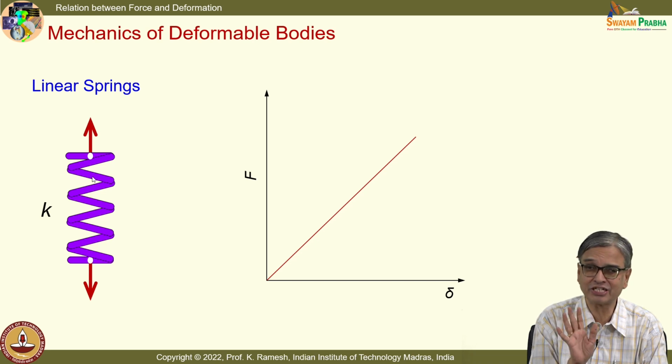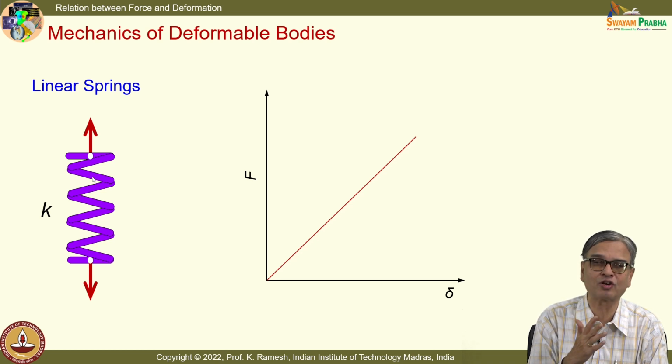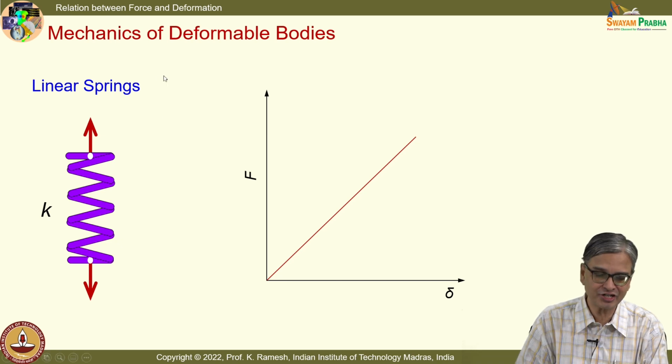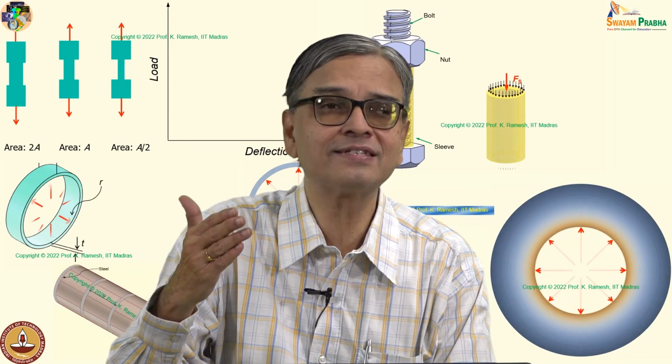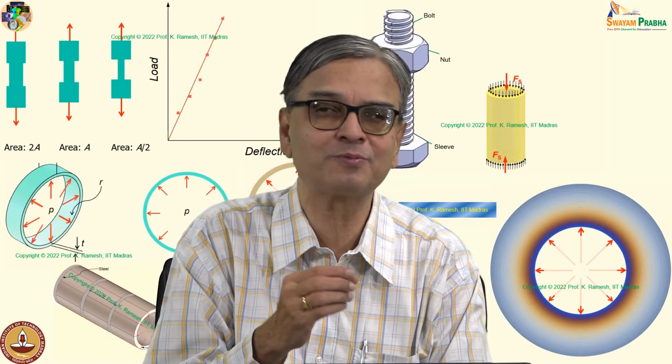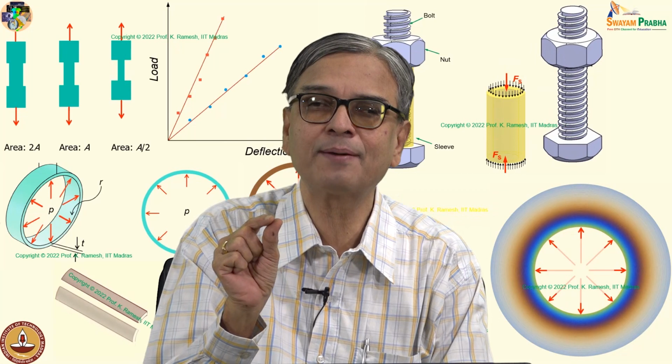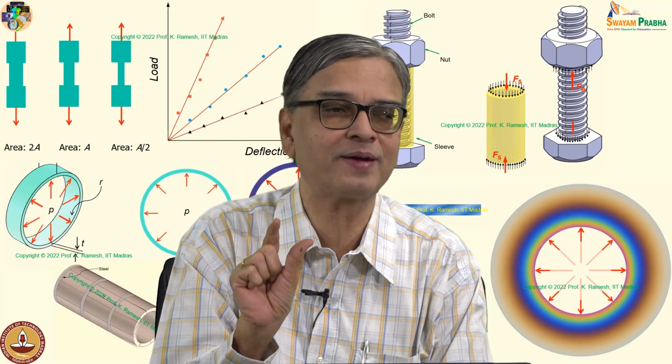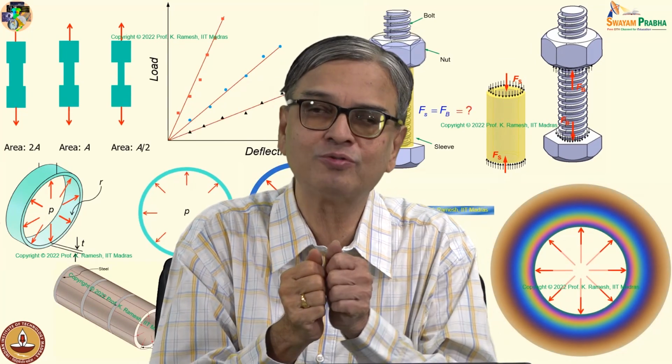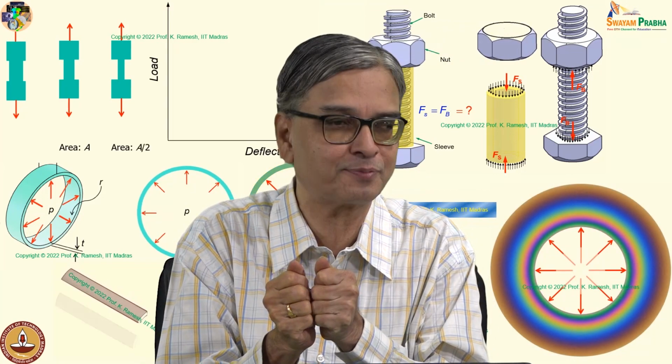It is not simple tension. What aspect we exploit for our understanding of tension or torsion or bending from spring is its linear relationship between force and displacement, and also its principle of recovery, because with a spring you can easily compress and release your hand, and it comes back to its original position.